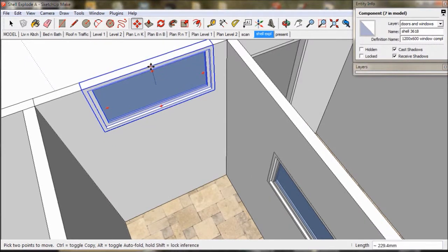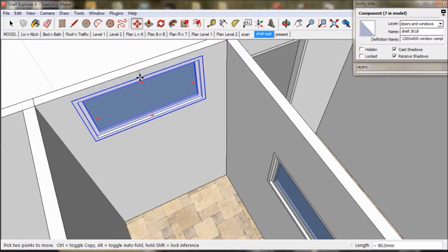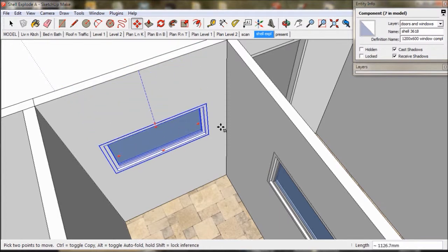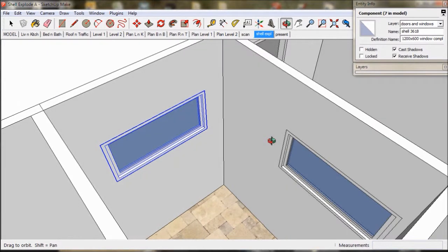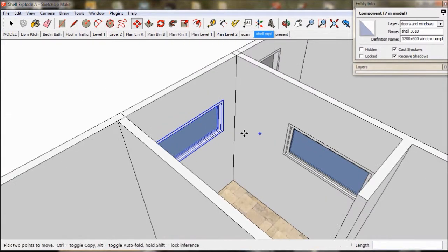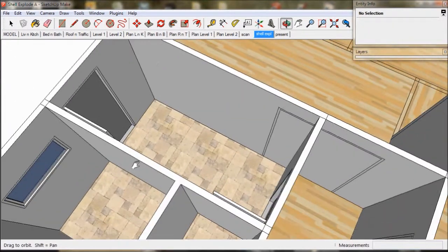Click on that point, then move the window up to the top of the wall and slide it back and forth. A light blue dot will then light up to show you the midpoint of the wall. So click on that spot. We click again and slide the window down and just tap the down arrow to lock in the blue direction. Now move the cursor to the old window to reference the height we want and click again. Now we'll delete the old window.